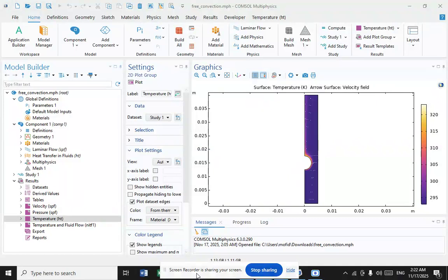In the theoretical analysis of free convection flows and heat transfer, the laws of momentum, mass, and energy conservation at certain boundary conditions are used. The Boussinesq approximation of weak thermal convection is widely applied. For example, density deviations from a mean value are considered to be negligible in all the equations, except for the equation of motion where they are taken into account in the buoyancy force term.